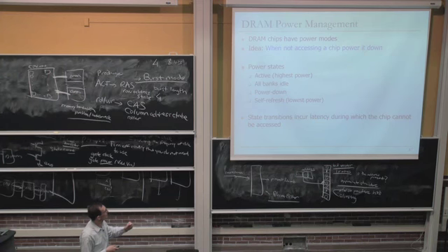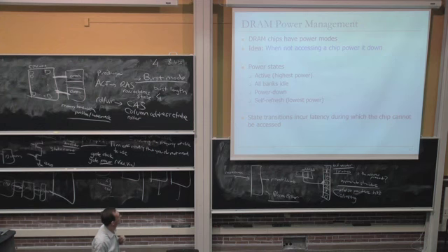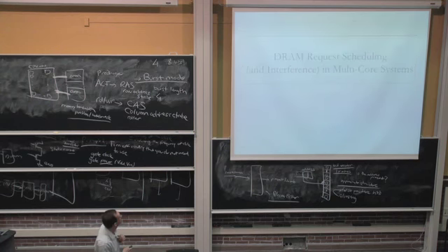Now, when your cell phone is turned on, and if you actually need to access something in memory, and the chip is in self-refresh mode, there's some latency it takes to get the chip out of that mode to enable the next access. And that's the longest latency. Because this is the lowest power mode, it takes longer to get out of it, because there's setup time associated with what the chip is doing.